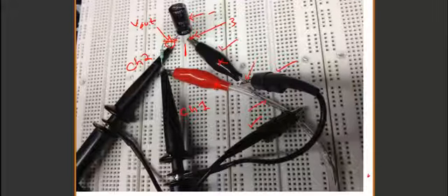This is the way that you connect the oscilloscope to an RL circuit. For the RC circuit, and the other configurations, RL, LR, only the location of C and R is going to be changed, or instead of a capacitor you may have an inductor, but everything else is going to be the same.